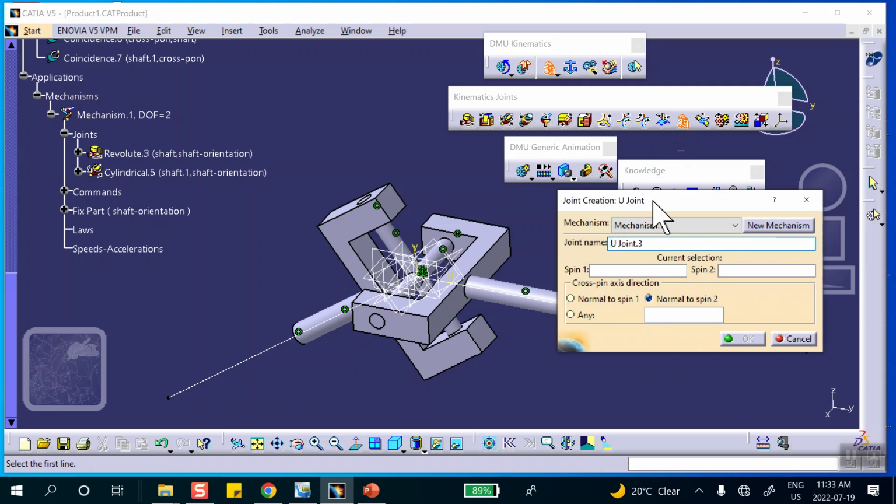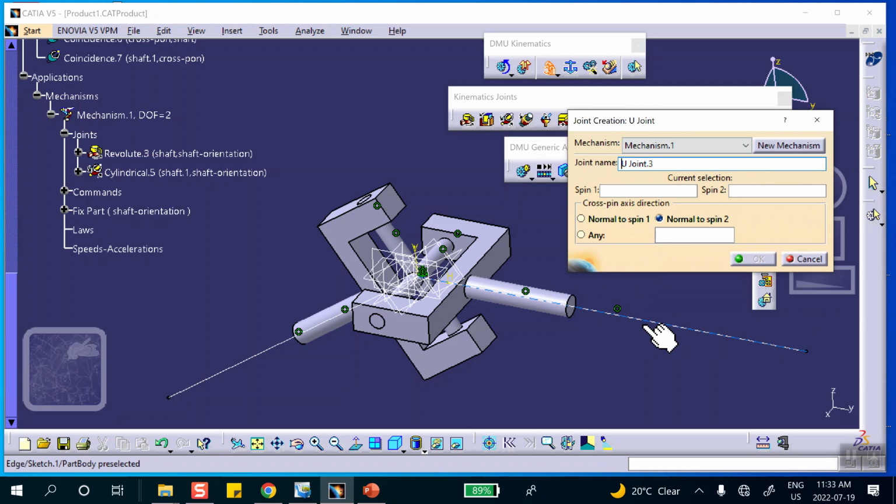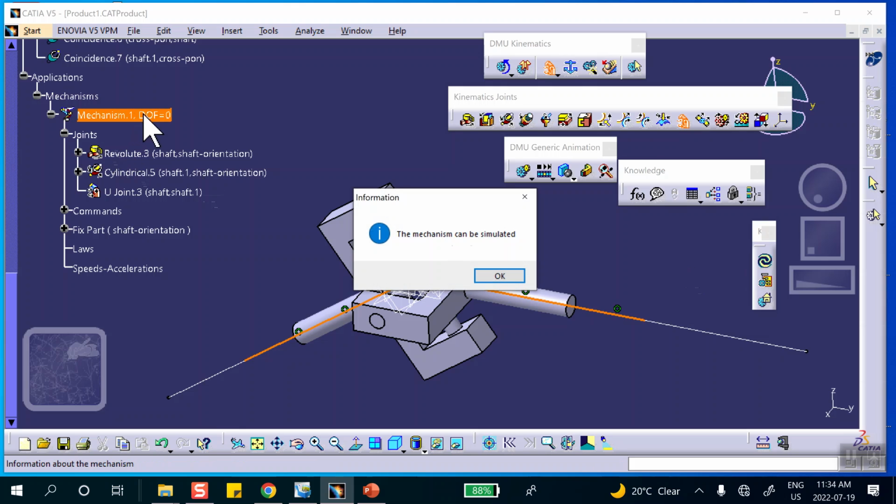Click on it. The mistake that I made was selecting this orientation line. I have to select the axis of the cylinder. See that? Not this, the axis of the cylinder, right there, the solid shaft. And for the second one, do not select orientation. Select the axis of the cylinder. The mistake that I made in both the 8:30 and 10 o'clock class for the second spin was selecting this orientation, whereas it should have been the axis of the cylinder. And this is fine. Leave these things the way they are. Say OK. And it says degree of freedom is 0.